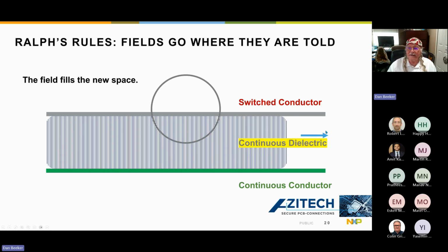The other thing, though, is it has no idea what's at the other end because it hasn't gotten there yet. So it takes time for it to go from the left side to the right side. It's only 6 inches, or 150 millimeters, per nanosecond. It's not moving very fast, even though it's the speed of light. This is one of the things that you have to consider.